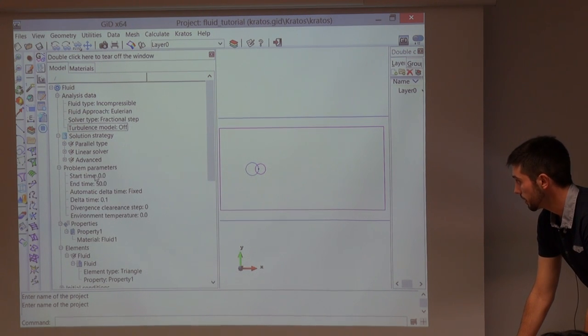And we will define the time stepping. We have here the time we want to start, 0 is fine, and in the final time I entered 50 seconds. I want to use a time step of 0.1 second, so I just wrote it in this little box that appears.